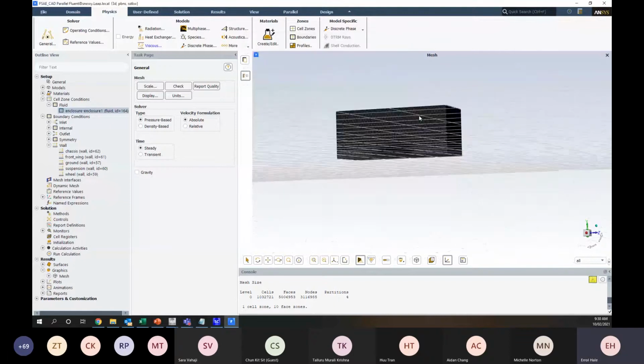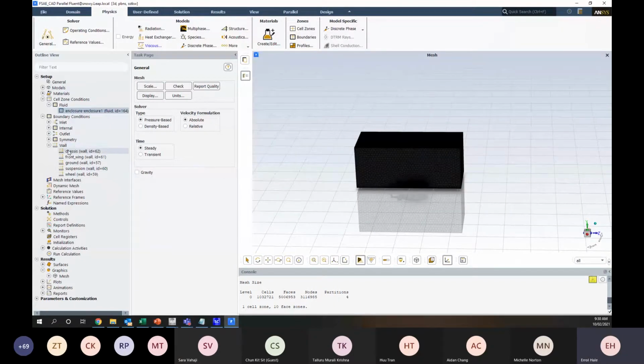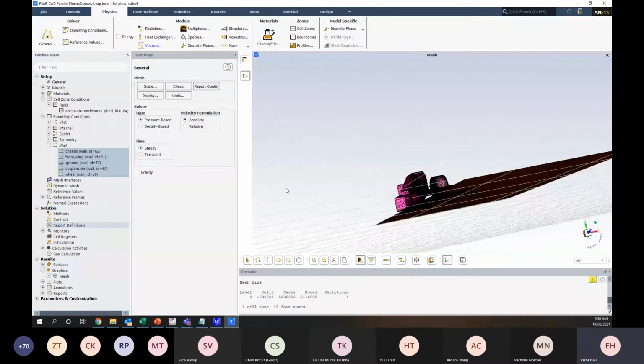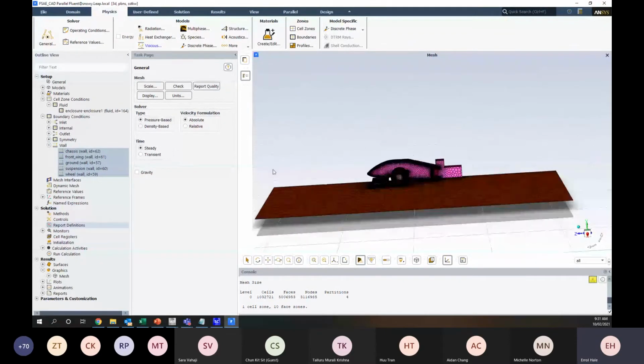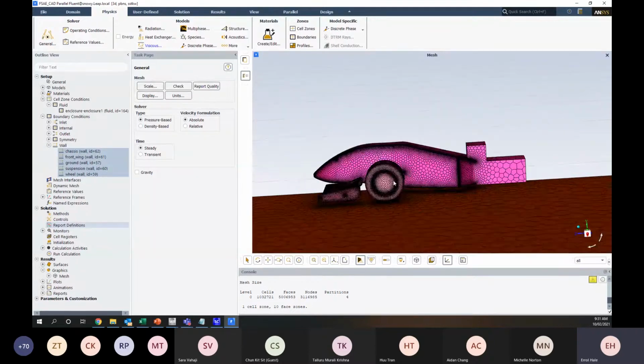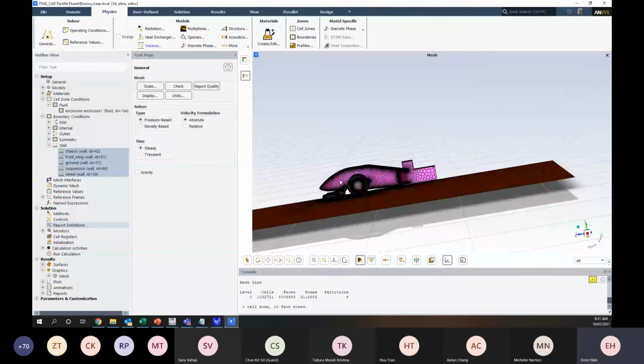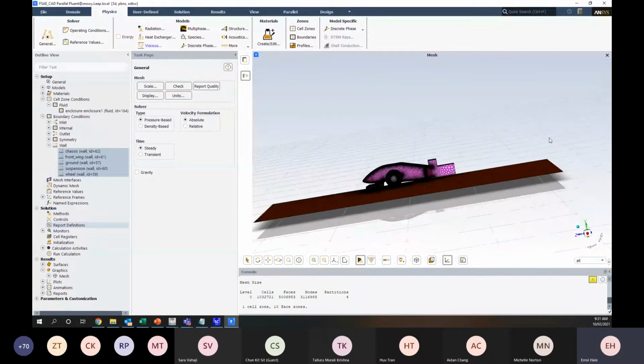So can I comment on the minimum domain size to be used? Yes, I can. It's really important that we have a large enough domain to capture the flow field. For a given flow velocity, the flow will come in at a constant velocity across the cross section, and it will be disturbed by our geometry of interest. We'd like to see that flow field return back to a steady, constant value before exiting the domain.